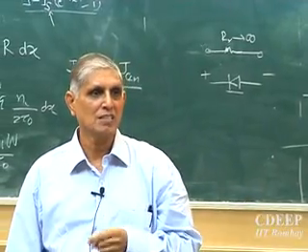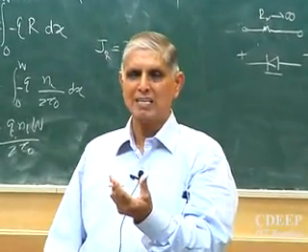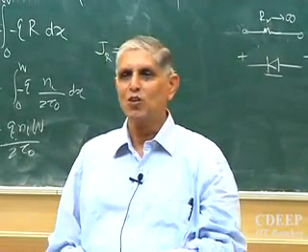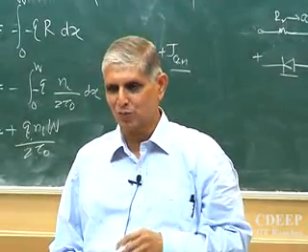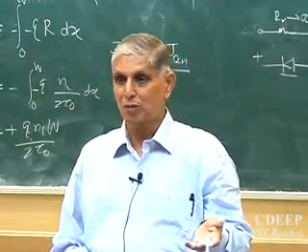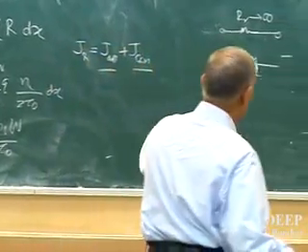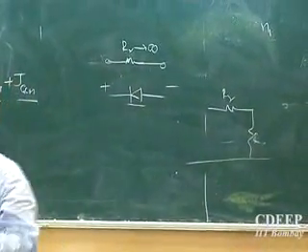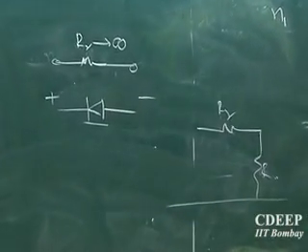Is that clear? So for a diode, ideally if I use an ideal diode, you open it, solve it. For pseudo ideal, you put RR equal to some 1 megaohm, 100 megaohm. But in reality, RR may be 1 megaohm or so. In which case, depending on the other circuitry or other load ahead, that output voltage may be a function of the diode resistance itself. Is that clear to you?